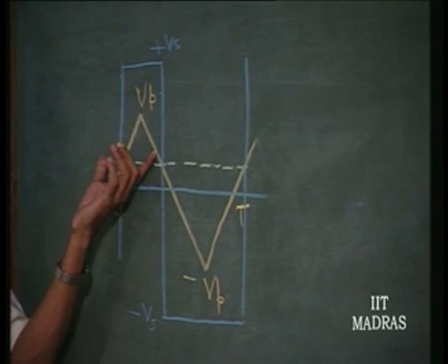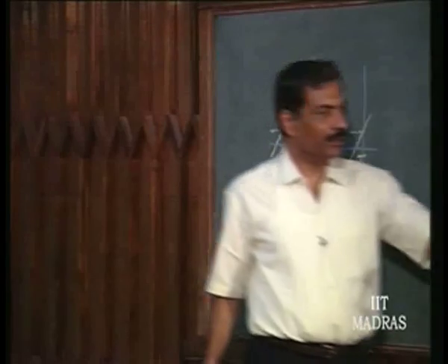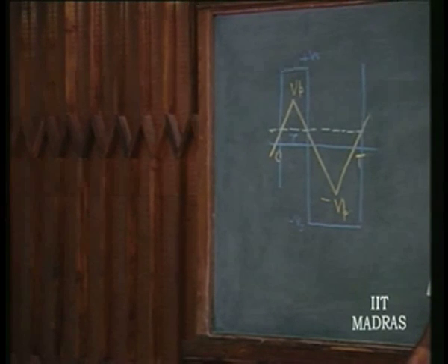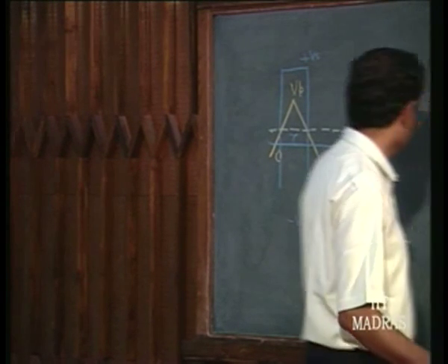Right. So, if I vary this, it will now generate an output pulse whose width is controlled by this voltage. So, this is nothing but a simple pulse width modulator, linear in the sense that the width is going to be linearly related to the control voltage here. Okay. So, let us see how it is.